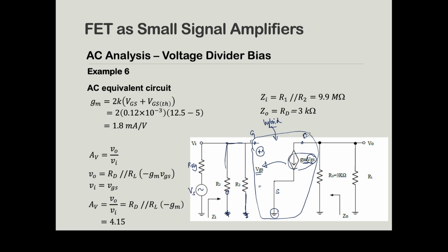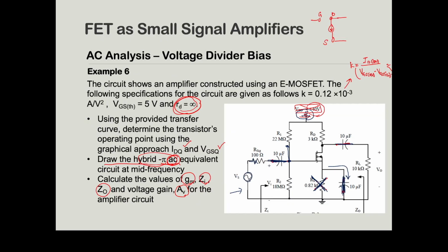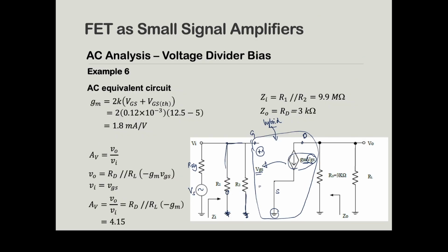Okay, you're going to have the drain terminal. And what will happen to your rd here? As the question said, rd is infinity, meaning that it will become open circuit. So no rd should be drawn here. There's no rd here, because your small letter rd is infinity.